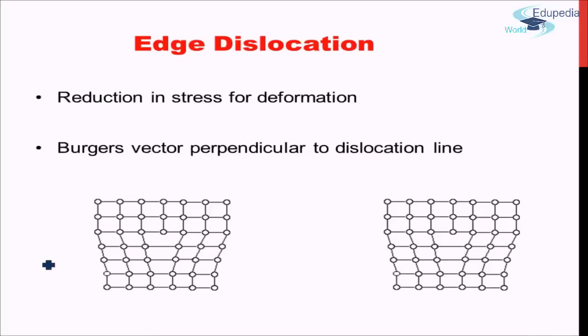Okay, so let me show you. Basically, to draw the Burgers vector, you need to complete a circuit around the dislocation line. What do I mean by that? Since this going inside the plane of the screen is the dislocation line, we'll draw a circuit surrounding that dislocation line.